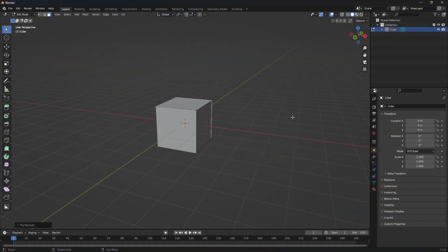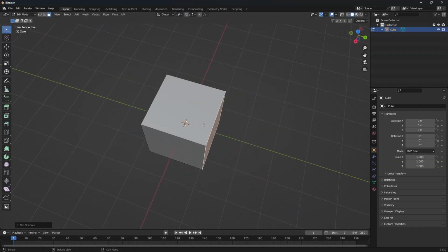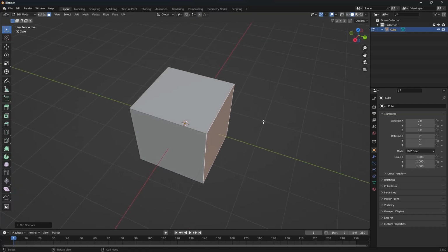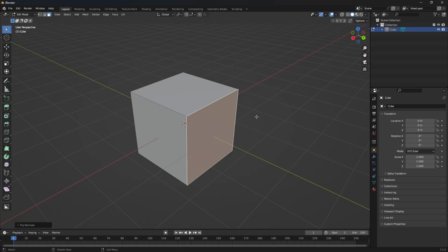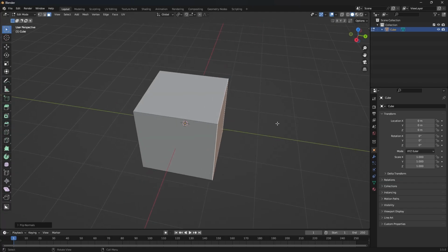All right, so here we are in Blender. And we're going to talk about two concepts, normals and quads, which are very straightforward, but they're unique to Blender. You may run into an issue where you've got a pretty normal looking object, everything seems to be quite normal with it, but it behaves weirdly. It doesn't print properly, or you try to move things around or apply modifiers particularly and something goes wrong. And it may be that the normals, that is the direction the faces face, inward or outward, has gotten flipped. This is actually quite common in the plane extension workflow.